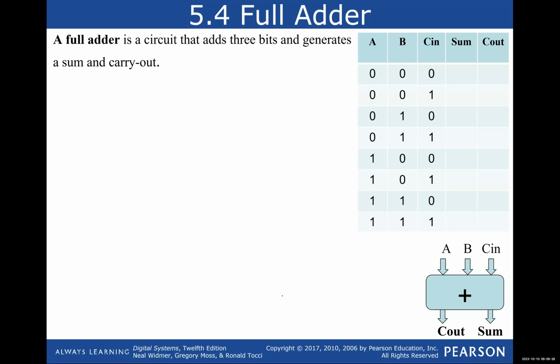Okay, and that's the one you're going to be designing in your lab this week. Okay, we're going to be designing the full adder. So the full adder will add 3 bits. Okay, now we know where the 3 bits are. 2 of them are from the 2 main numbers we want to add together. The third one is the carry input in case that I have it. Now let's address all the different possibilities that can happen when we're adding 2 numbers plus a carry in. And let's see what the sum and the carry output are. We're going to use Boolean algebra, not K-map. We're going to use Boolean algebra rules to find the expression. And then we're going to find the relationship between the full adder and the half adder.